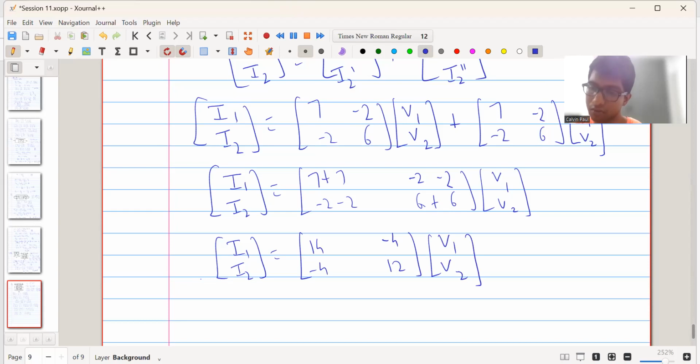So this is the effective Y parameters of network 2, which consists of two parallelly connected copies of network 1. And we just found out that you add the Y parameters of both the networks and you get the equivalent Y parameters of the overall network. So when the networks are parallelly connected, it is best to represent the individual networks in terms of Y parameters, and then we add the Y matrices of those networks, and then we get the overall equivalent Y parameters for the network.